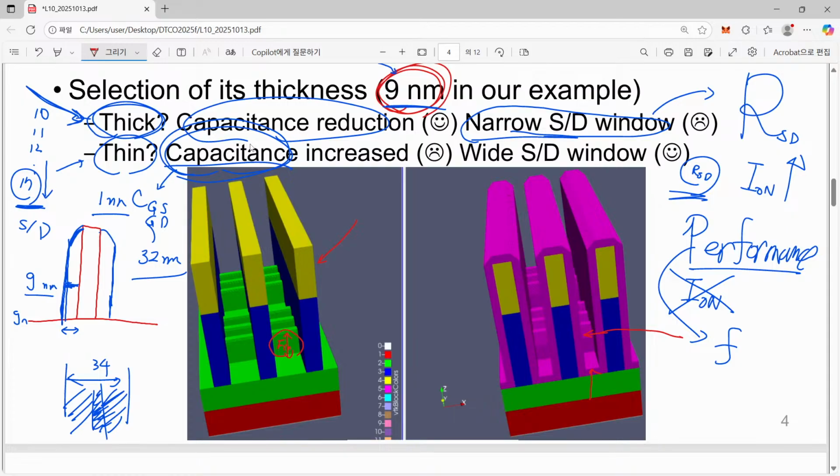So if we make just a 9 nanometer etching, then what will happen? Then we can completely eliminate this one, good, and also this one, good, and also the one here can be eliminated. However, what will happen to the one on the fin? The top part will be etched away, but still we have a relatively short fin sidewall, and this fin sidewall should be, well,